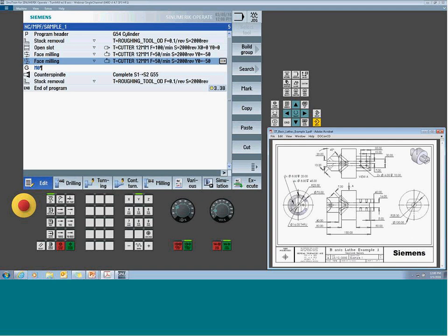I'm sure it's hard for you guys to see, these are hidden lines or hidden holes. So the exact same 2 hole locations, and the nature of us flipping the part over, it's the next positions. It looked from the top view with the hidden view that you have 4 holes. We actually only have 2, so that's what we're going to be plugging in. We're going to do this top hole and that lower left hole, then do them again on the opposing surface.